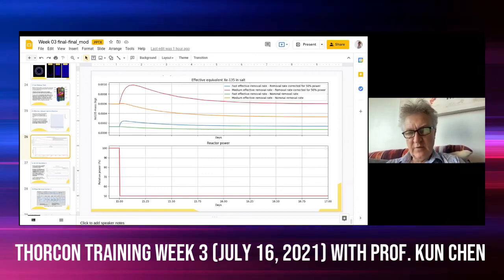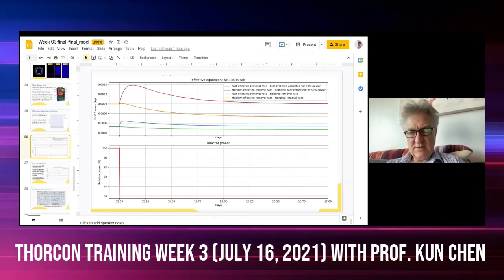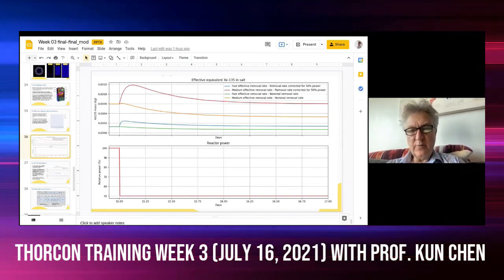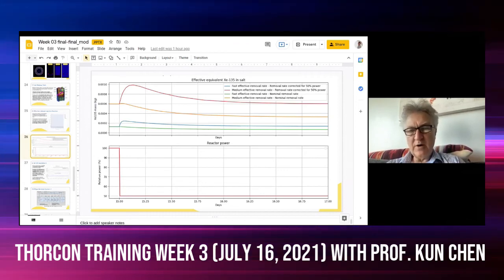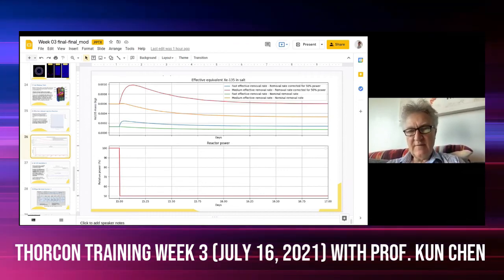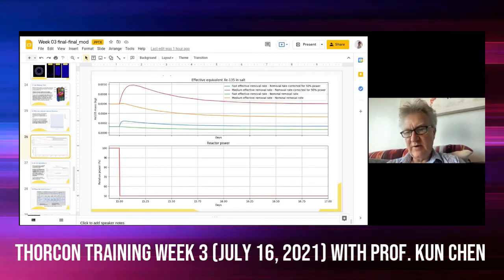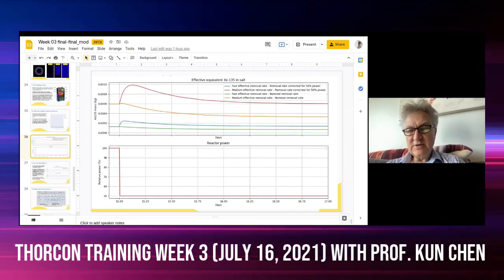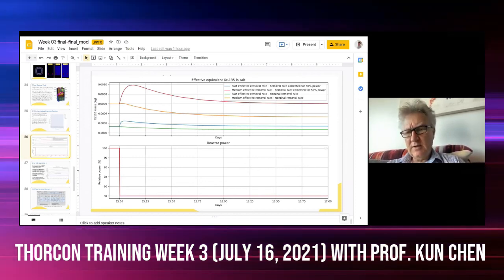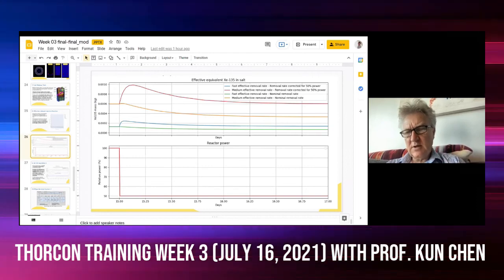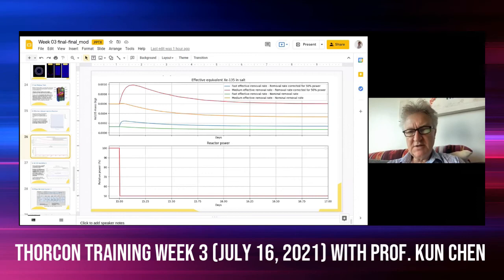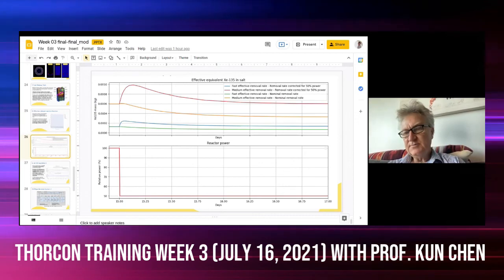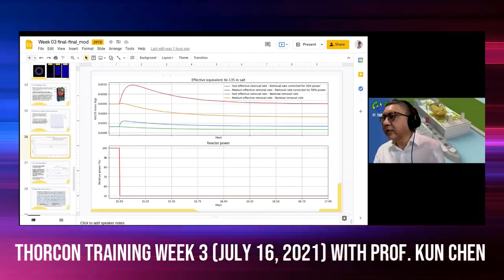Containment for the first level is the can, which is steel at about 350 degrees C and under no pressure, or under 1 bar of pressure. The silo cavity is basically under very slightly negative pressure and is steel at about 100 degrees C. And then the hull is steel, then 3 meters of concrete, and then steel. So pretty strong containment.